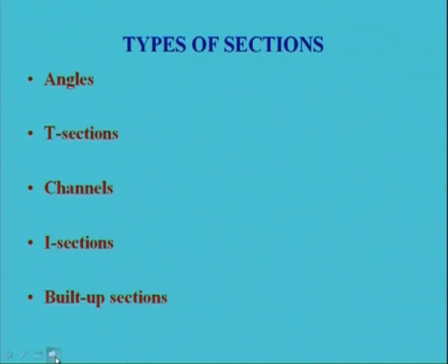So, what are the sections available for beam member? First thing is anybody can use a beam member as rectangular or a trapezoidal as per the requirement of the site, as per the requirement of the structural analysis. The designer has to decide whether he will go for rectangular section or trapezoidal section or circular section or some other sections, right. In RCC building we will see in most of the cases we make the beam as a rectangular section. Sometimes we make it as a T section, right.